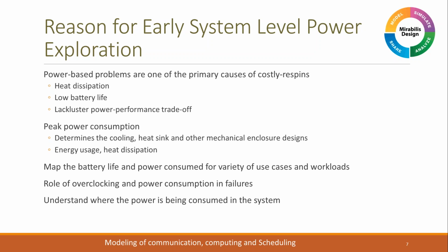The other aspect is your peak power consumption. A lot of times there might be spikes that are a result of multiple things happening at the same time, which if used properly in a management process could be scaled with offsets so that spike never occurs. How does that help? You can reduce your surges, which will in effect improve your battery life, and improve the maximum power available for a longer period of time.